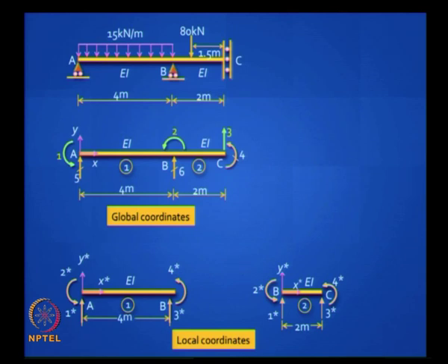And if you had to write down the loads in this particular problem, do we have any nodal loads? No, they are all distributed loads. There is no support settlement given also. Now you have to write down the transformation matrix. What does it look like? Can you try the 2 transformation matrices? Well, they are identity matrices.